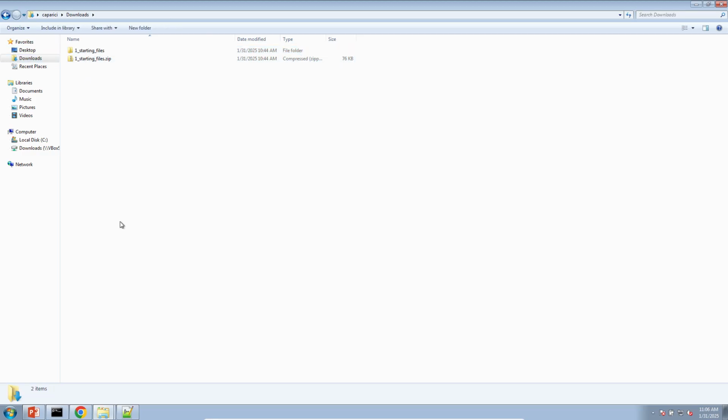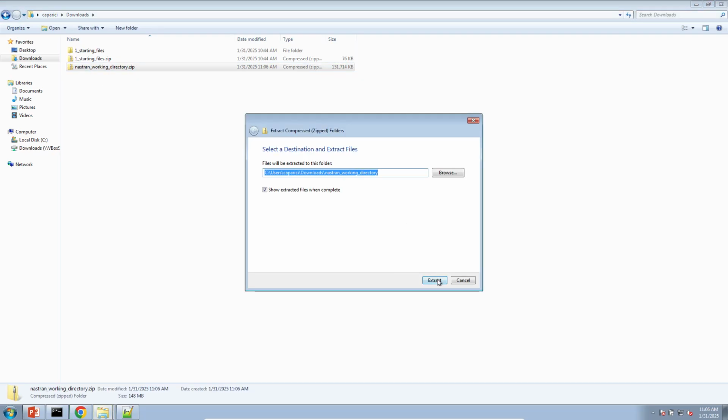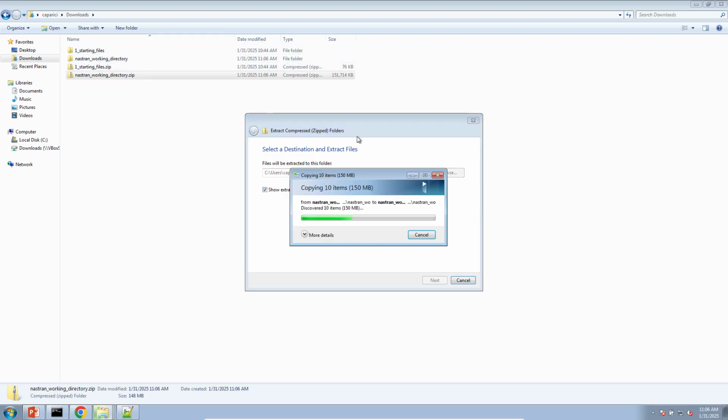Remember that we didn't update each initial value for the OUU variables. It was going to be too time consuming for us to do that, and no one wants to watch me do that for about an hour. So there's a faster way to update all those design variables. Let's go ahead and extract the contents and open the Dakota input file.